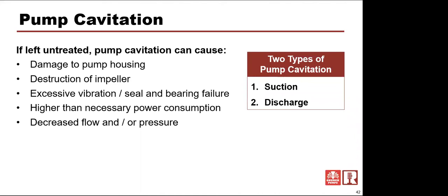It creates vibration in the pump. Sometimes you can even feel that on the outside of the casing if you put your hand on the outside of the casing as it's running. Please don't put your hand in the area of a rotating shaft. It's not a good thing. I don't speak from experience, but I hope never to make that mistake.